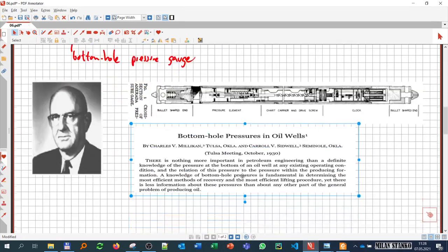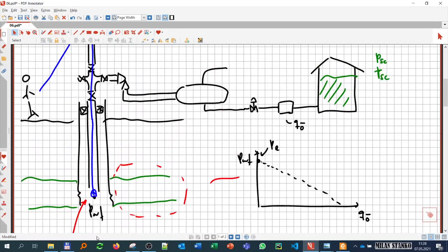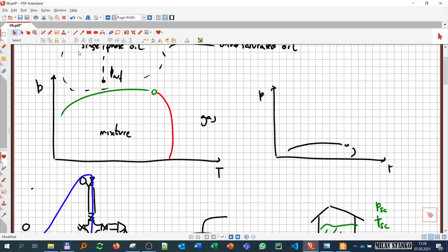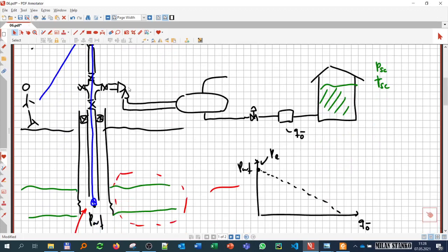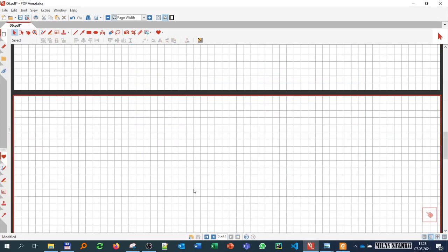So if we were going to do that experiment, we have already this in place. We have our well, remember, a vertical well. We have our assumption here that we only have single phase flow, that means we're doing our test in this region. And then what we do is change the choke. So if you do that experiment, first let's see what happens in time. In time we have our QO, and we might start at a very high value.